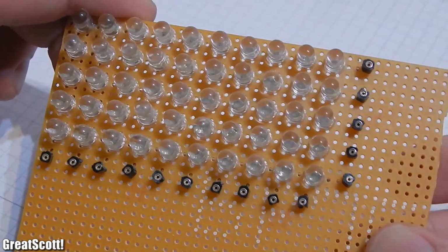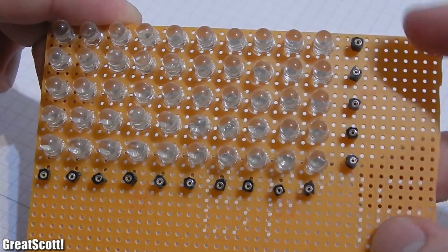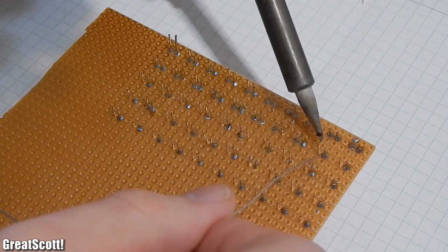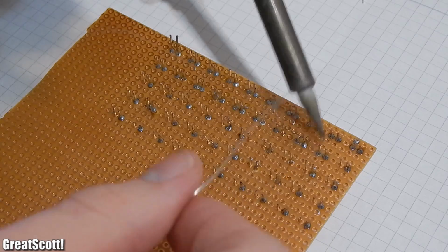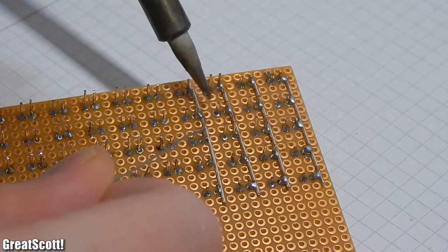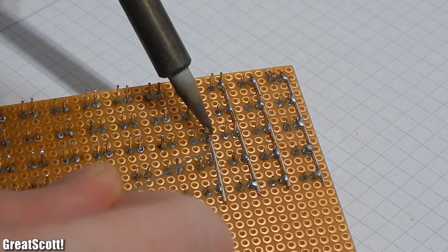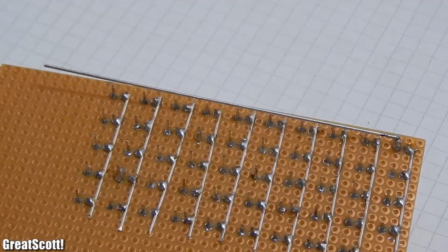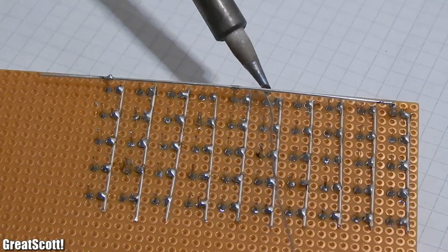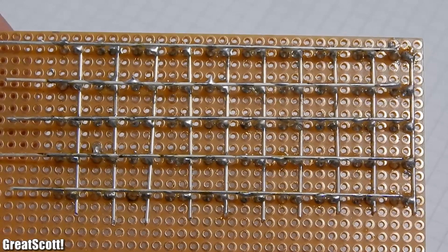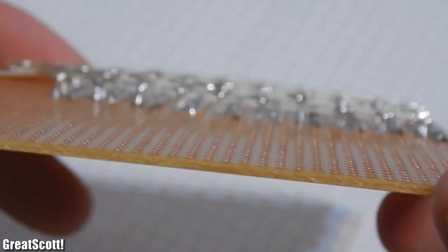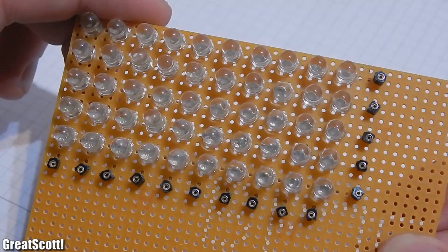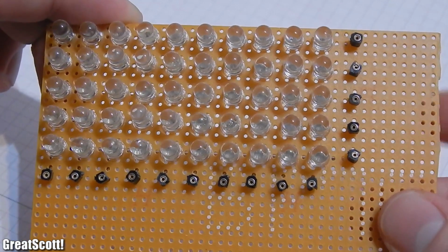I think the principle is easier to explain with an LED matrix, so let's build one. I just solder my LEDs to a PCB like normal, but now happens the magic. I connect all cathodes or negative pins of all LEDs in one column and repeat this process for all columns. Now I connect the anodes or positive pins of all LEDs in one row, and I made sure that the anodes and cathodes touch nowhere. And it's done. Now I have my 5 anode rows right and 10 cathode columns down.